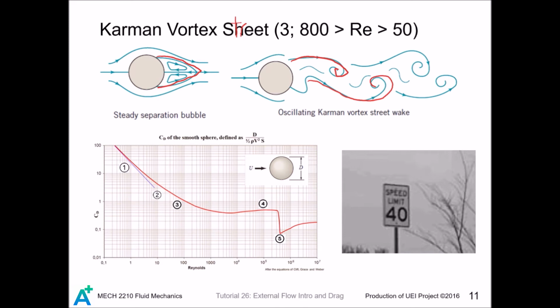And if you have looked at the simulation in class, you see that this road sign will be oscillating. If you have not studied fluid mechanics, then you may think that the wind direction is always changing. But in fact, the flow direction is always in one direction, and it is the two competing vortices that make the road sign oscillate. By the way, the term wake here means that the pressure in this region is particularly low due to the flow separation.